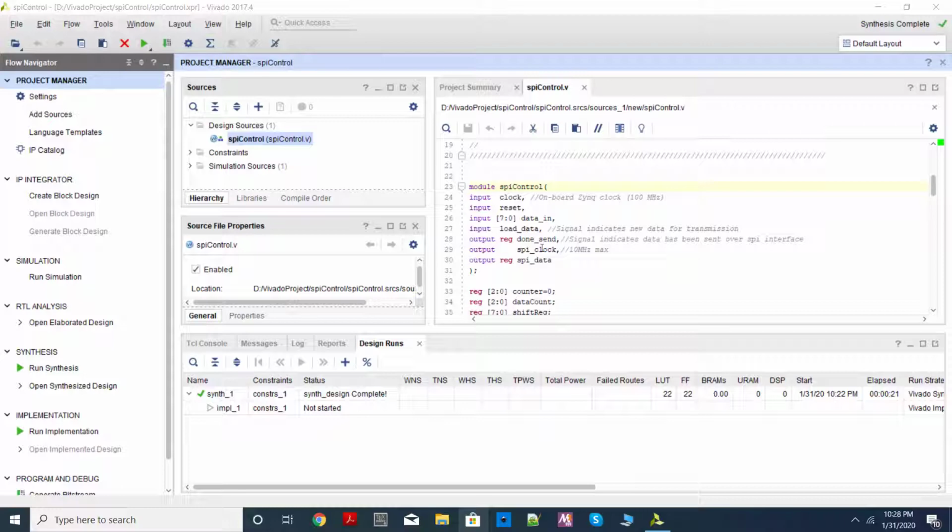You can decide which signals should be added to this chain in Vivado, and Vivado will synthesize that scan chain for you. So it will synthesize all the circuitry for you, and during runtime you can specify a special triggering condition under which it should check these outputs, and those outputs you can see in real time on your screen.